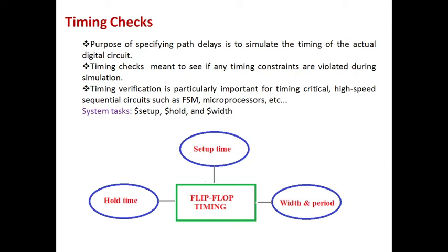So we call them flip-flop timings. Here we have the timing check system tasks $setup, $hold and $width, which are also specified inside your specify block.